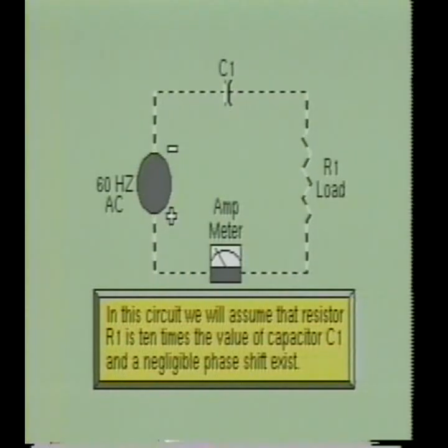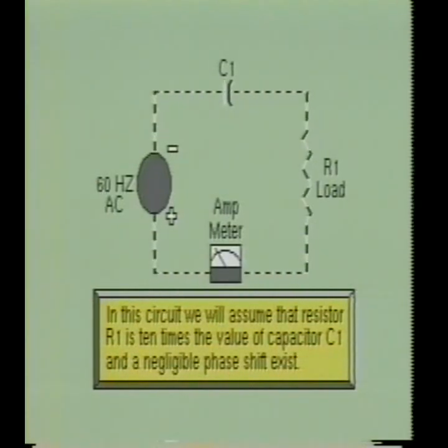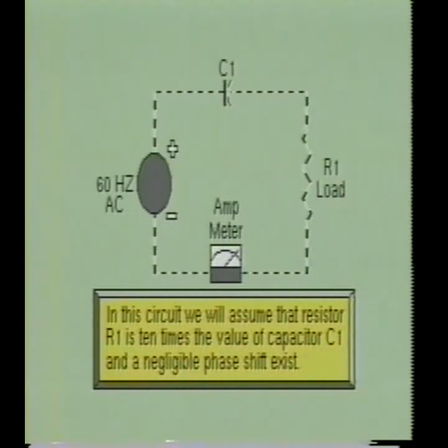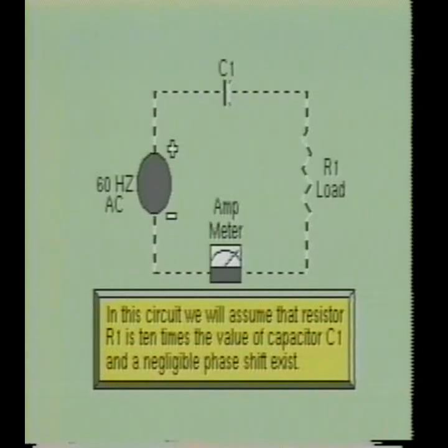After the sine wave has reached its most negative peak value and the capacitor has become charged, the sine wave starts back toward the zero reference line to start the process all over again. As the AC sine wave continues to alternate first in one direction and then in the other, the capacitor will continually charge and discharge through the load of the circuit. As you have seen, the load resistor sees a current flow first in one direction, then the other. As far as the load resistor is concerned, the alternating current is flowing through the capacitor, even though no electrons actually pass through the dielectric.